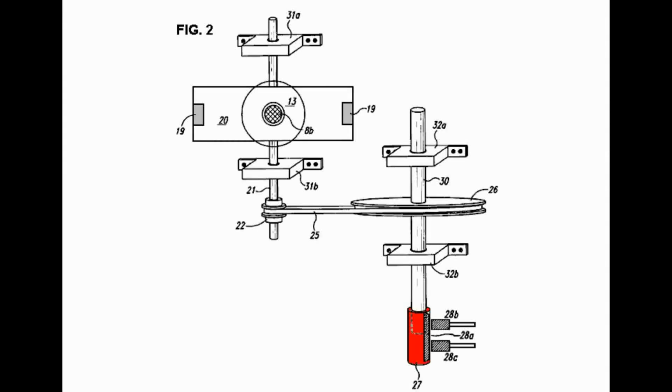Figure 2 is mechanical perspective top view of the monopole motor of the instant invention without electrical circuitry. Stator 18A consists of coil 13, which is comprised of three separate coil windings: power coil, winding 13A, trigger coil, winding 13B, and recovery coil, winding 13C. Pole piece 18B is at the end of the stator 18A.